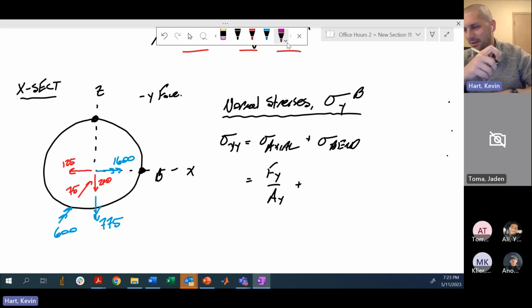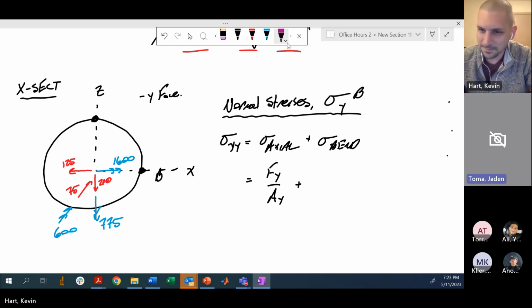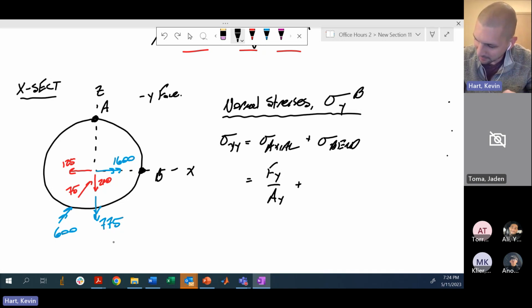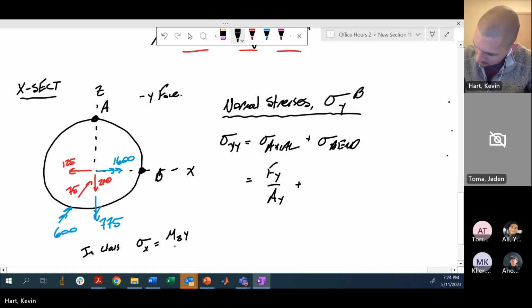The bending moment visualization is probably the most difficult. I might have done this wrong the first time, but I said that there was no stress created from that moment because of the z variable, because isn't it moment in x times z over moment of inertia? Yeah, so in class we derived the following, that looked like this with a negative sign in front, right?